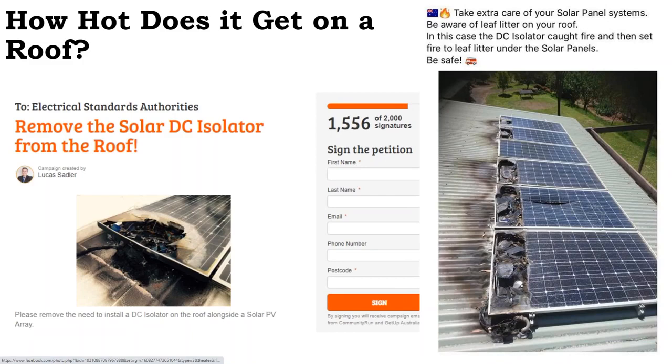You can assume the cold temperature side of things is going to be a little bit harsher. And generally, when you're looking at your temperature conditions, you're using the record low, but they let you get away with the ambient high because that hotter temperature, to some extent, is going to start dragging back your system performance.